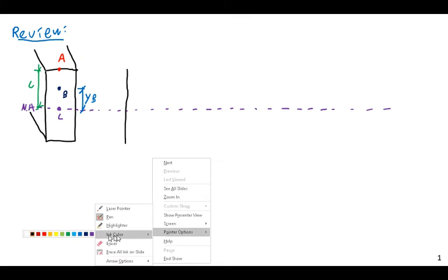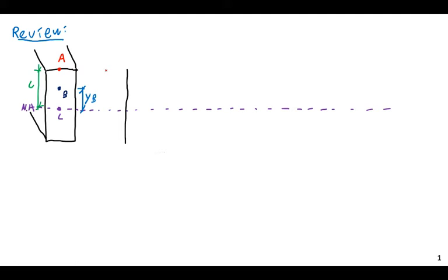Okay, so here we are. Let's say I have something like this. This would be the bending stress in the beam, except it would actually be linear. Squiggly linear is approximately linear. So we have this kind of linear-ish bending stress. And then we have a sigma in tension, our maximum sigma in tension, which will be positive.